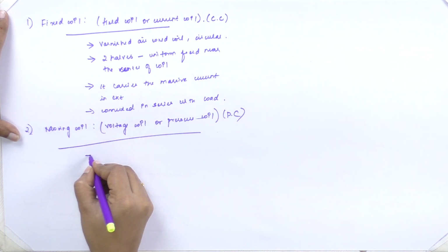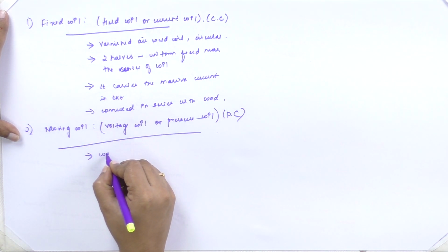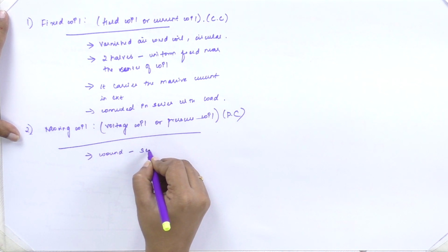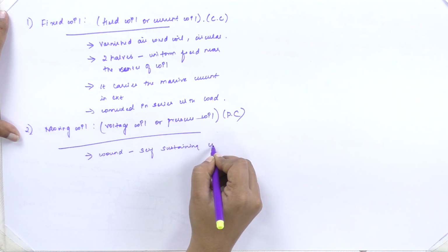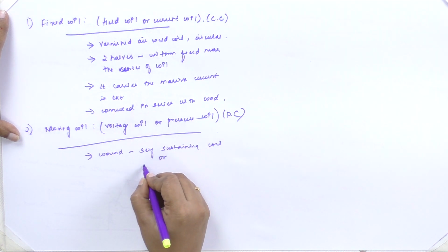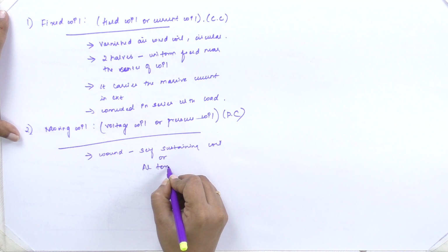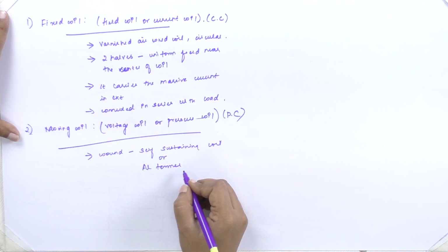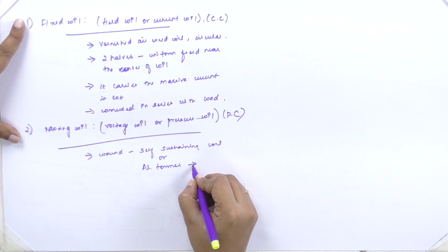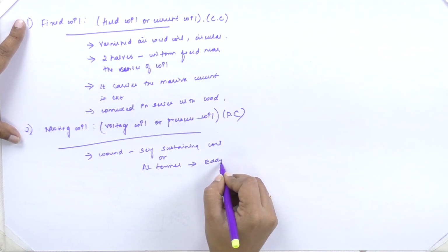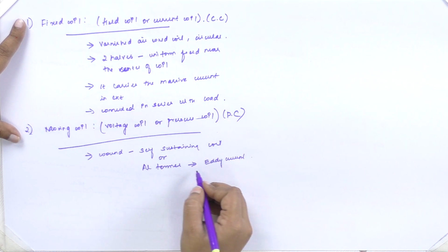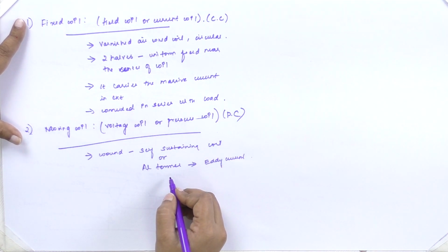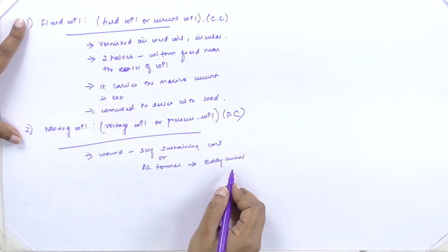This moving coil will be wound either as a self-sustaining coil or wound on an aluminium former, as in the case of a permanent magnet moving coil type instrument. If an aluminium former is used, then eddy currents will be induced which cause errors in the system. So, the thickness of the aluminium former is made as light as possible in order to reduce the eddy current.